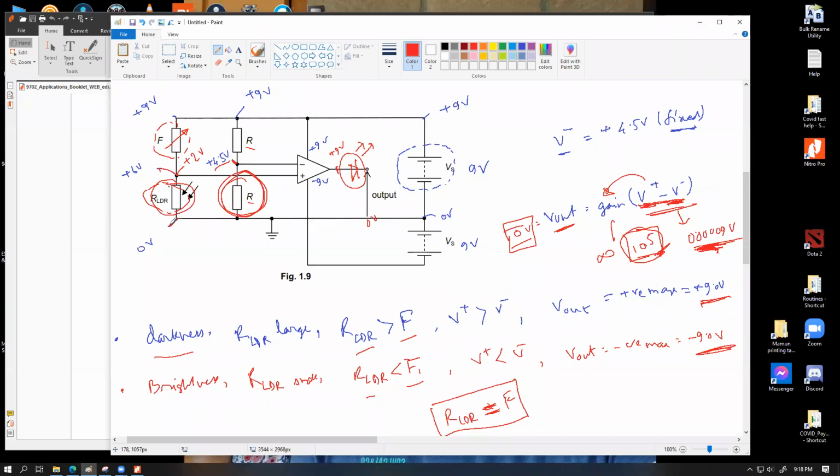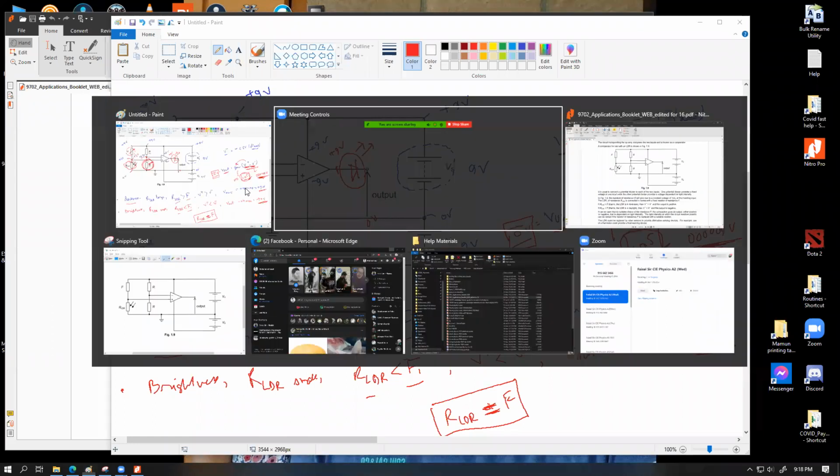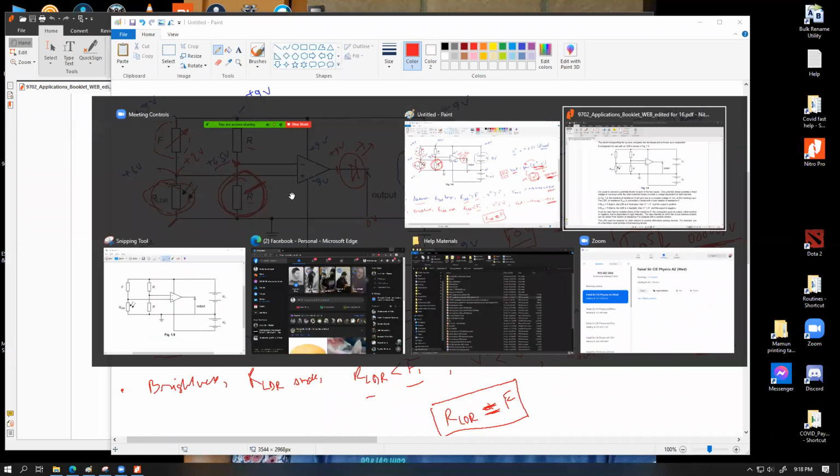For making better sense, I always say that this is going to consume one part of the voltage and then the remaining will be available over here. And to be honest, in all cases, that remaining voltage will be entirely consumed by this resistor. So if you are trying to find out the voltage value of this point exclusively in a single step, simply calculate the voltage that is supposed to be consumed by the lower one. This will make the calculations a bit simpler. Okay, let's have a look at the next part.